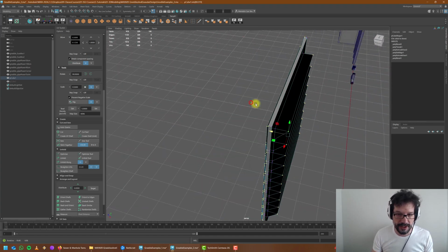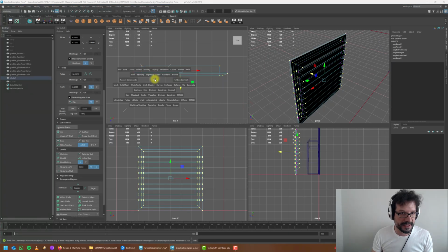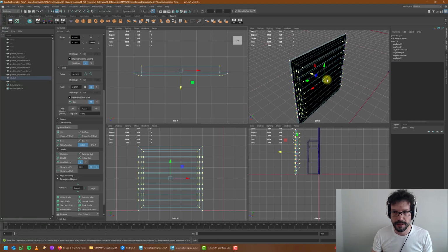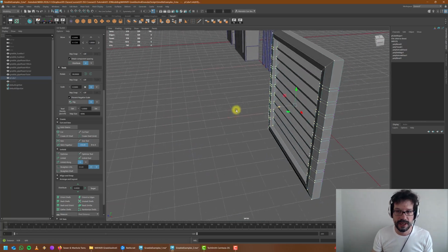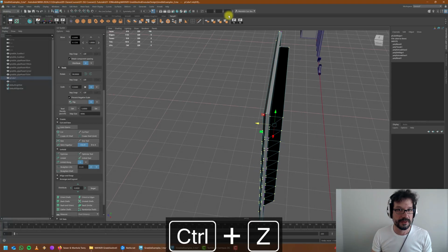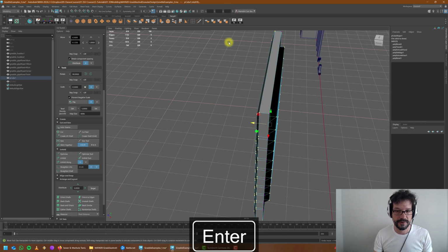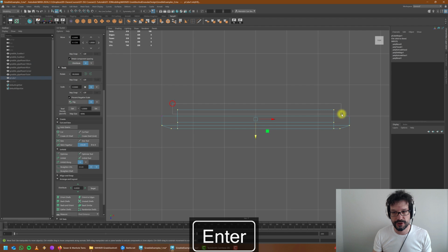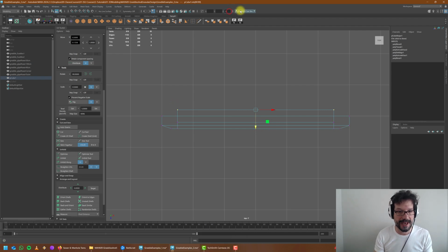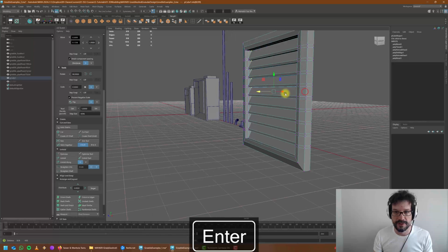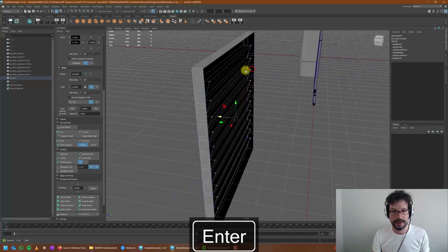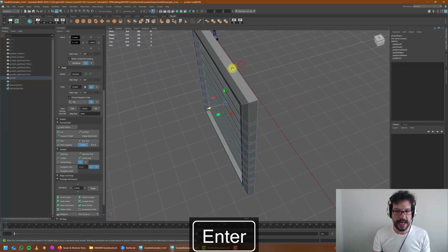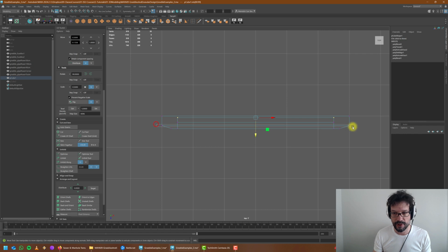You see what I'm trying to get at? Maybe let's grab everything in here. We're going to push them in this direction. So hide the crime, so to speak. This is the Z direction. Let's push them in the Z direction for 2 centimeters, and then I'm also going to grab these and push them as well. It's not going to be a 45-degree angle, but I can push them even a bit more to fully clear that area.